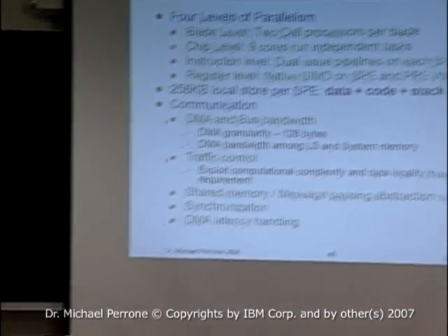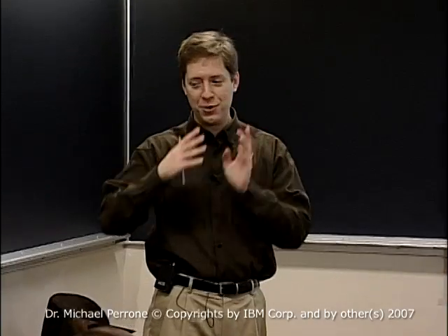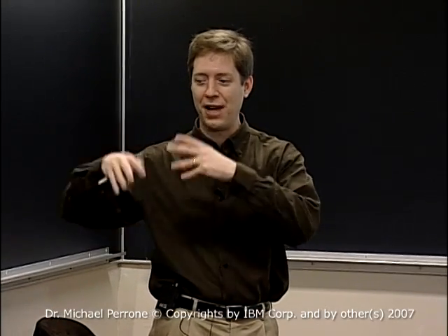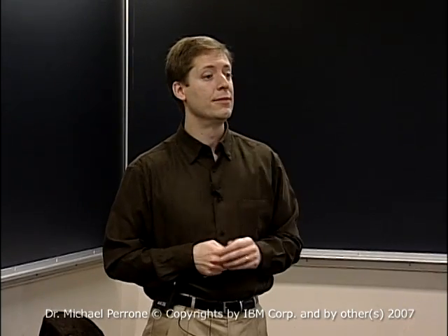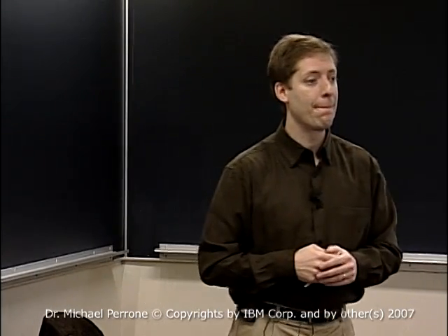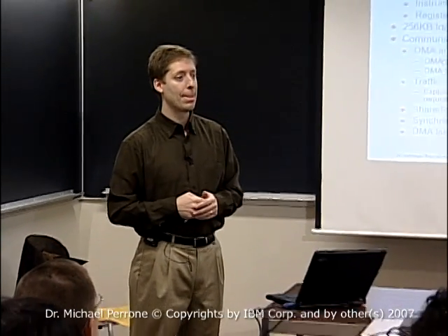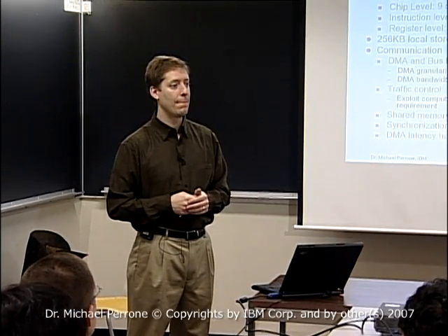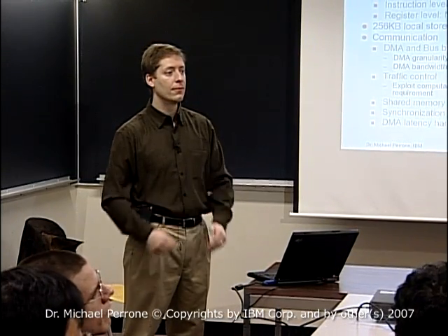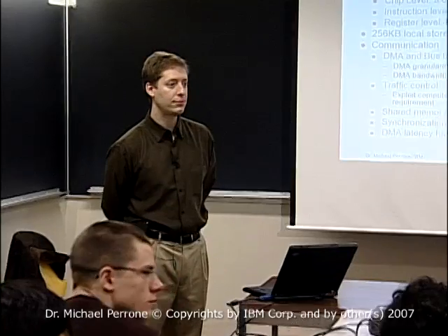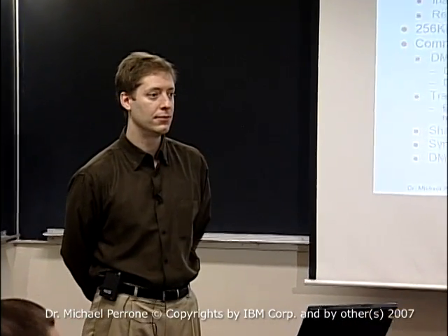Yeah, and that was done for power reasons, right? Get rid of all the space and all the transistors that are doing all this fancy out of order processing to save power. I've been playing around a little bit with some programming on the SPE, and I find that I keep having phase ordering problems with pipelines. I ended up doing things that look vaguely like synchronous algorithms, right? Like all of the data manipulation, then do all the arithmetic, then do data manipulation again. And again, I'm only able to use half the processor at a time. So, right, that's for other people who start hacking on this.